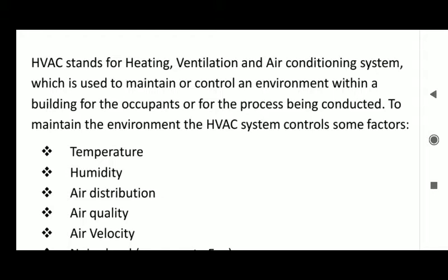This is the amount of water in air. You understand humidity more because presently, as I'm speaking to you, we are experiencing what they call harmattan in Nigeria. That harmattan is telling you that we have little or no water in air. So what does that lead to? Drying of your nose. Any clothes you wash at this time get dry faster. But don't forget, when your nose gets dry, all the air within your nose will get dry alongside. So it gives room for more dust to enter your lungs, and this gives you some airborne diseases. So within a facility you are maintaining, you should ensure that your humidity is within a regulated standard.